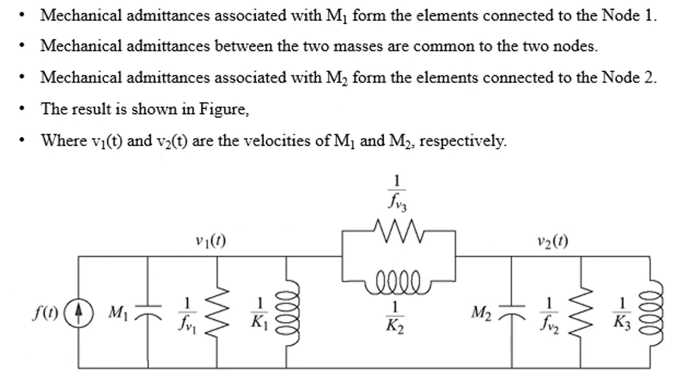Dear students, now from the equations obtained in force-velocity form, we will make our desired parallel analog of the mechanical system, which is also shown in the figure. As said earlier, this system has degree of freedom equal to 2. In a translational mechanical system, all the impedances associated with the first test point occur in parallel to the first node.